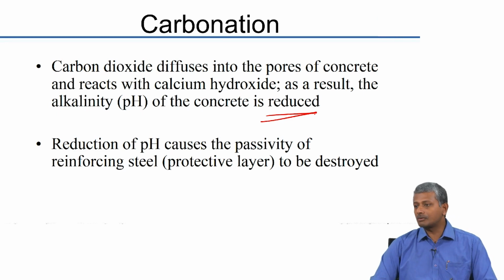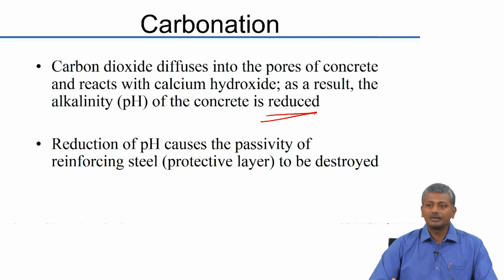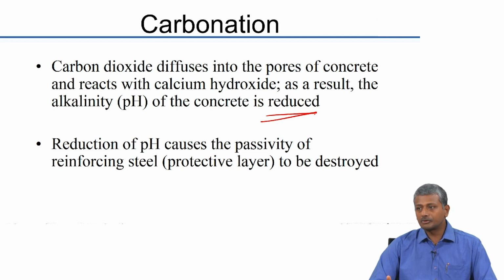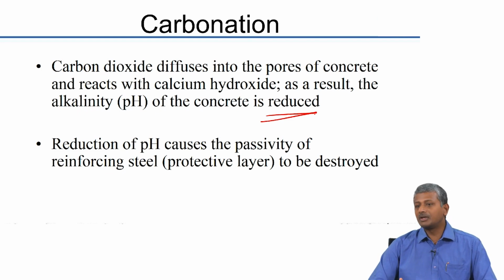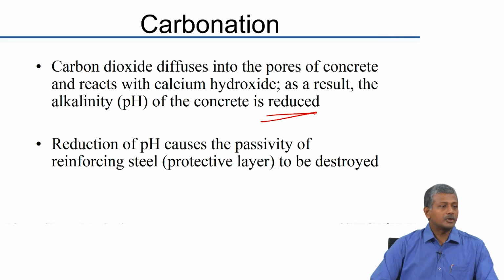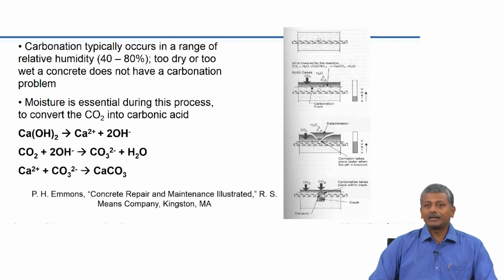Otherwise, the properties of concrete are actually positively increased. For example, the strength of concrete is going to be enhanced because of carbonation, because you are converting calcium hydroxide into calcium carbonate. So, if you take plain concrete and subject it to carbonation, you may actually register a strength increase with time. But if you take reinforced concrete, the corrosion of the reinforcement is going to get initiated because of reduction in pH caused by carbonation.